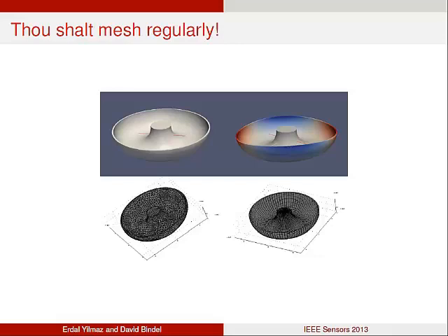The reason is that the number of cells we are using for the revolution creates a mesh which might or might not be capturing the symmetry of the vibration or the perturbation mode together. Or if you are looking at multiple modes or mode couplings, then even a structured mesh in this three-dimensional way might not give you good accuracy for the perfect geometry.